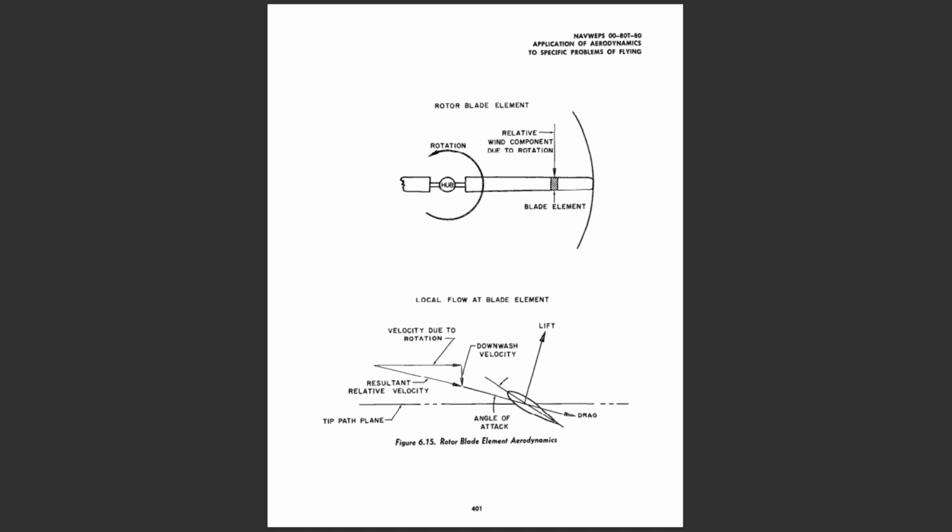As in the airplane, there is one angle of attack or blade pitch condition that will result in the most efficient operation. Unfortunately, the typical helicopter rotor operates at a near constant RPM, and thus a constant true airspeed, and cannot operate at this most efficient condition over a wide range of altitude and gross weight as the fixed-wing airplane can. The airplane is able to maintain an efficient angle of attack at various altitudes and gross weights by flying at various airspeeds, but the helicopter will operate with a near constant rotor velocity and vary blade angle to contend with variations in altitude and gross weight. If the rotor could operate within a wide range of rotor speed, the efficiency and performance could be improved.